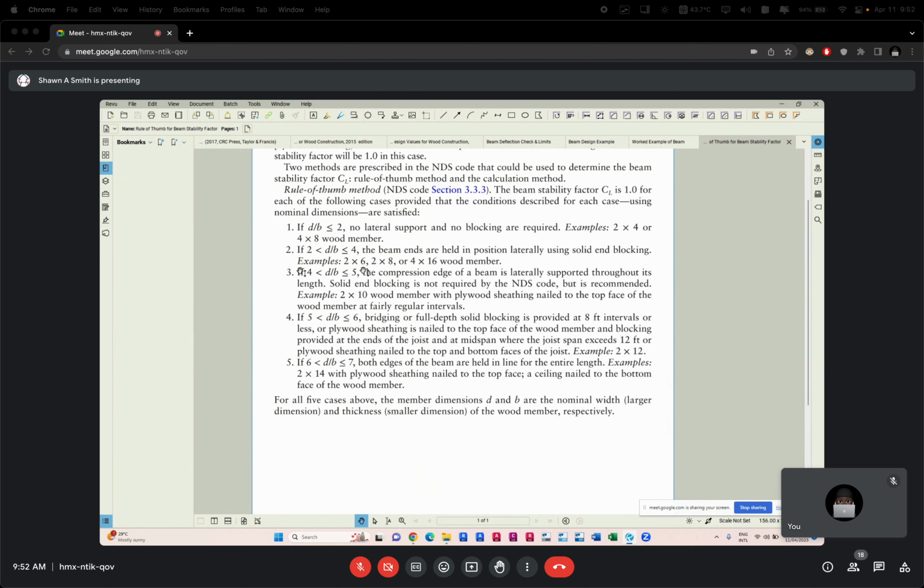Something like these might come out, and you'll be looking to check to see if in fact the beam is laterally restrained. Because if not, then CL is not 1. For your scenario, you always get CL equal to 1, but not necessarily in the form that we always give it, saying the beam is laterally braced by a slab or by flooring board or whatever.